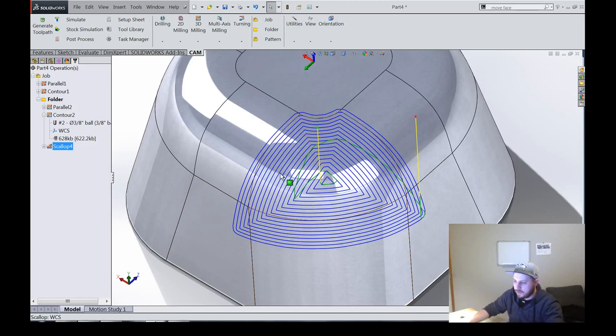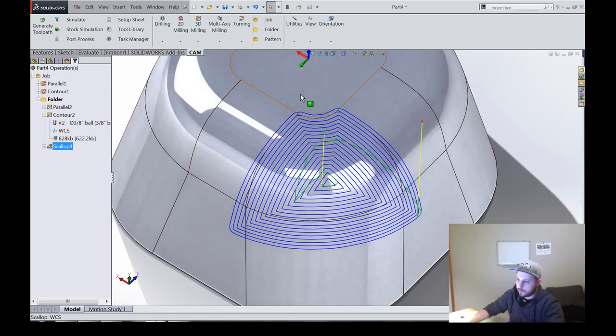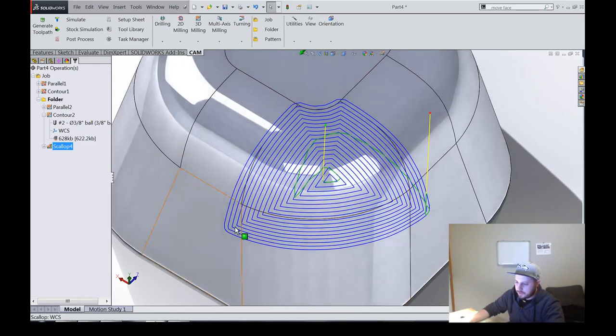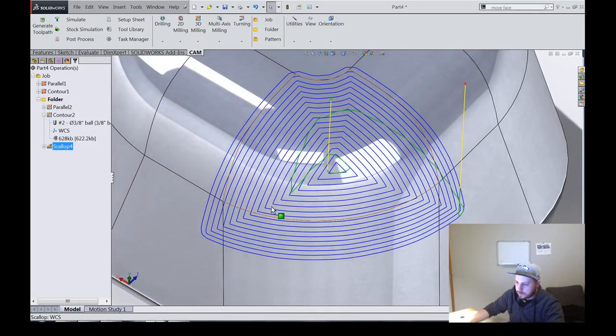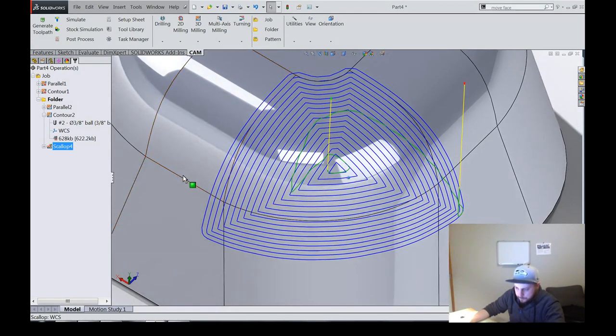What we want is, I don't really care if it's going this direction or this direction, but what I don't want it to do is just abruptly change. And you can see I had pointed out before that there were those sharp corners. This pocket collapsed almost immediately, and so on every single one of these corners, you're going to have that same cusp that's going to develop in these corners. It's going to be especially bad right through here.